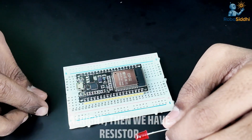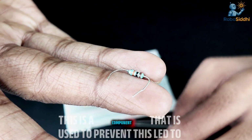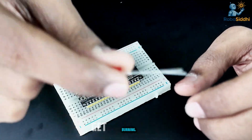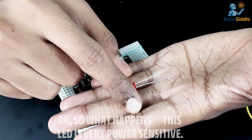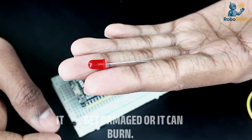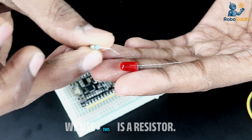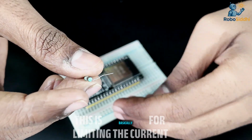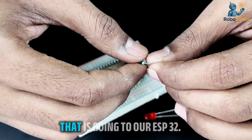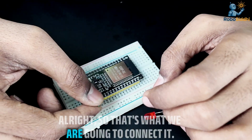Alright. Then we have a resistor. This is a component that is used to prevent the LED from burning. The LED is very power sensitive. If you apply too much power, it can get damaged or it can burn. So to avoid it, we use this resistor. This is basically for limiting the current. So that's what we are going to connect.